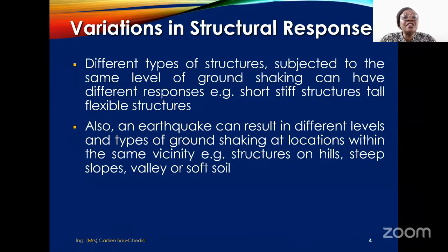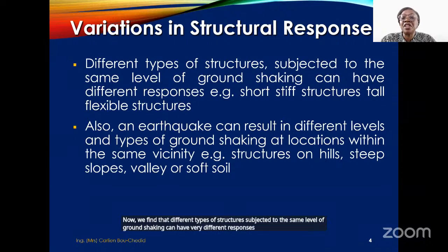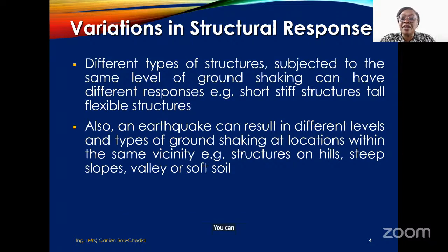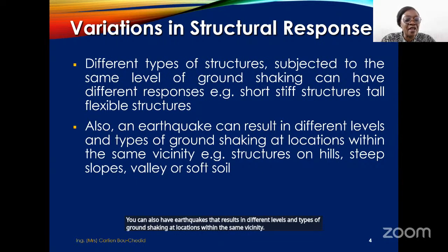Now we find that different types of structures subjected to the same level of ground shaking can have very different responses. Sometimes because a structure is short and stiff, it may respond differently from a structure that is tall and flexible. You can also have earthquakes that result in different levels and types of ground shaking at locations within the same vicinity. So in the last lecture, we saw a whole area flattened and only 2 buildings left.